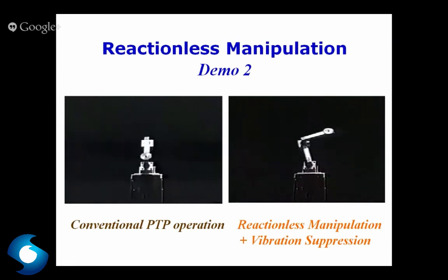This is something unique and special. After a clear understanding of the motion dynamics, we can make such an operation. This idea must be useful to damp out the vibration of such a space station-based long-reach manipulator arm. This phenomenon, this physics, is exactly the same as the previous example of the free-floating manipulator arm. With a very special trajectory of the endpoint, we can generate a manipulator motion that makes completely zero reaction back on the base.